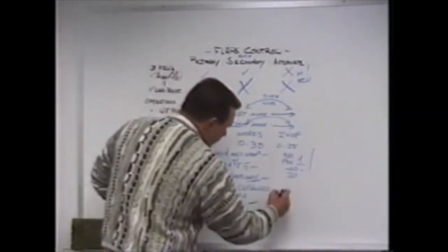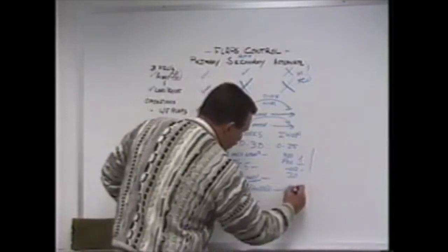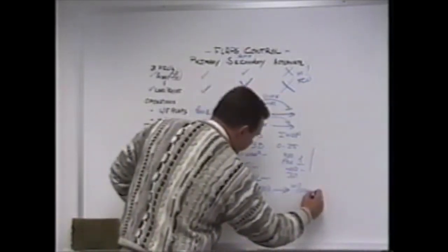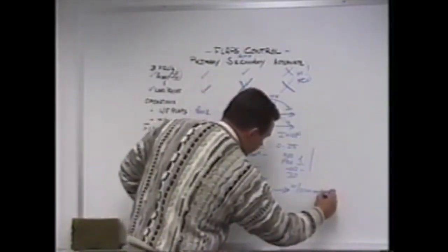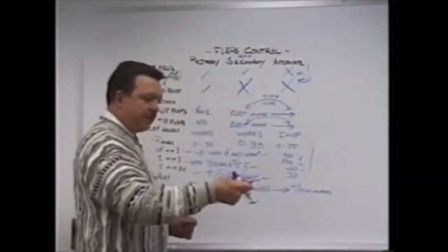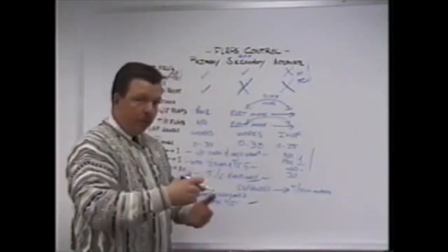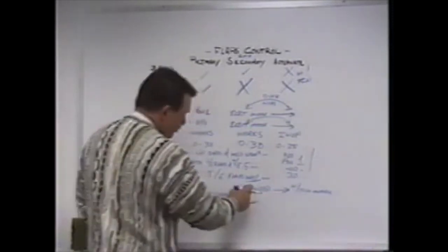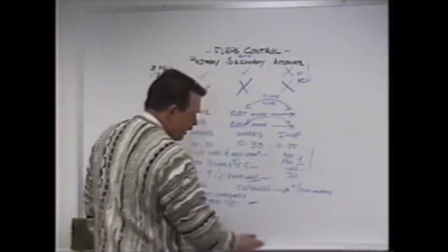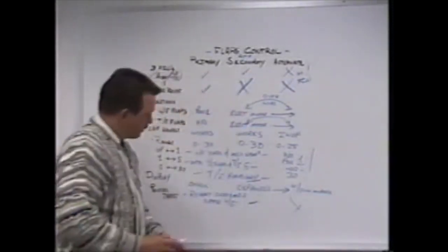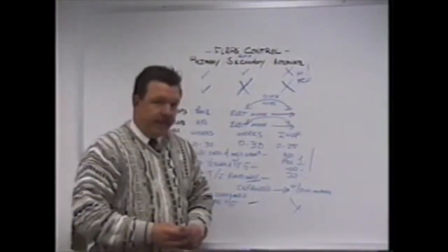The display is an expanded display with tick marks, because you need to know when to take that alternate flap extend switch to off when you get to the appropriate 10 or 20 position. So it's an expanded display, but it has tick marks on it, and going into reverse thrust is not going to affect leading edge flap operation.